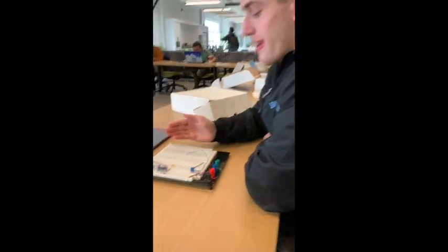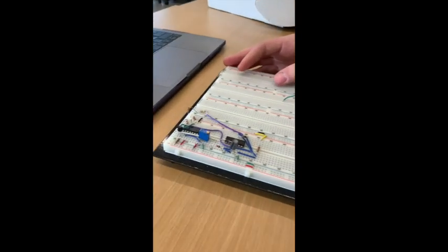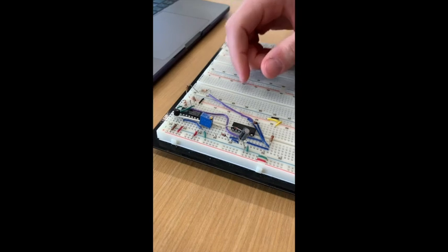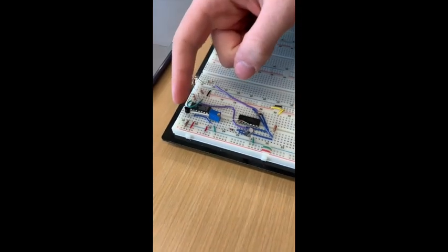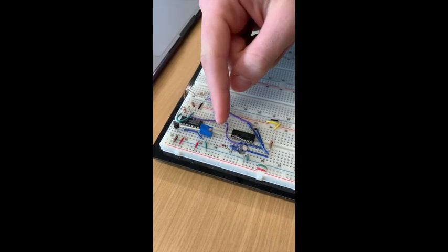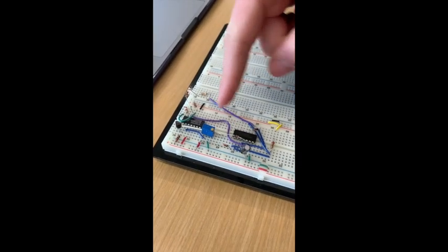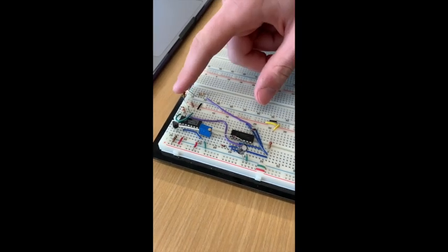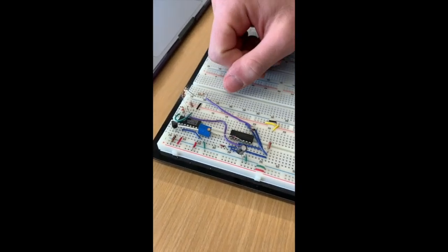Hello. Here we have our voltage controlled oscillator circuit, the final one from the overall lab. We have the voltage controlled oscillator source, the constant current source, which is impacted by the potentiometer. That goes into two diodes into a system of transistors. It also goes into a capacitor, and at the end there's a Schmidt trigger, which is where our output comes from.